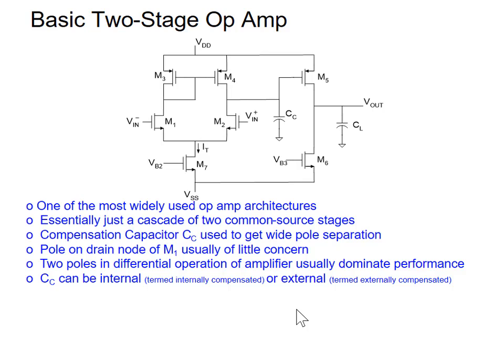So that pole is in the system, but it's not in the difference mode transfer function. It crops up on the common mode transfer function. Does that make sense? So we have eliminated a common mode pole by going with the tail voltage bias on the stage. This capacitor does affect the common mode gain characteristics, which we will talk about a little bit later. Hence, it affects the frequency dependence of the common mode rejection ratio.